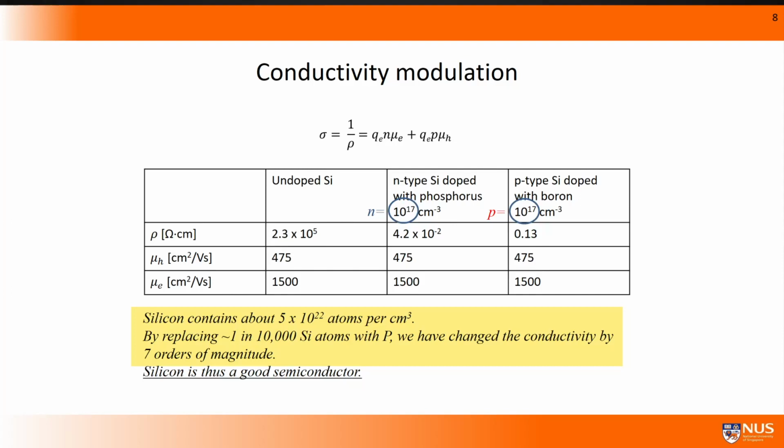If you instead doped it with boron, then the reason why the resistivity is a little higher is because the hole mobility is not quite as high as the electron mobility is. So if you have the same doping of phosphorus in a silicon wafer as you did with boron in another wafer, the N-type or phosphorus-doped silicon will be a bit more conductive.